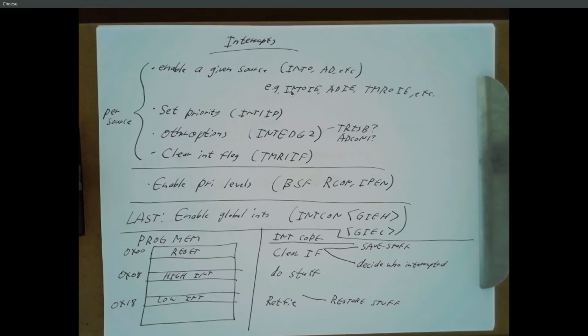Yeah? So is that usually if you have multiple interrupts that could possibly happen? Because otherwise you can do retfie 1, right? And do the shadow register. If you're only concerned with WREG, status and bank select, yeah, you can do a retfie 1 and that'll work great.